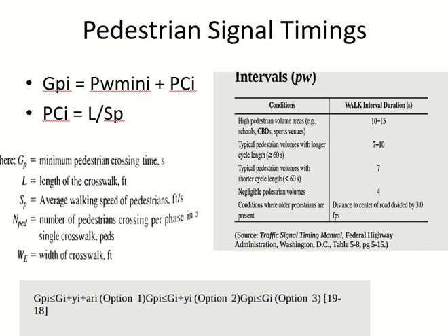If I am the pedestrian crossing and my signal starts blinking, what do I do? Move fast, obviously. Or pick up your child and prepare for that. But anyways, moving faster is a logical option. So for pedestrian clearance time, we take a slightly higher speed of the pedestrian.